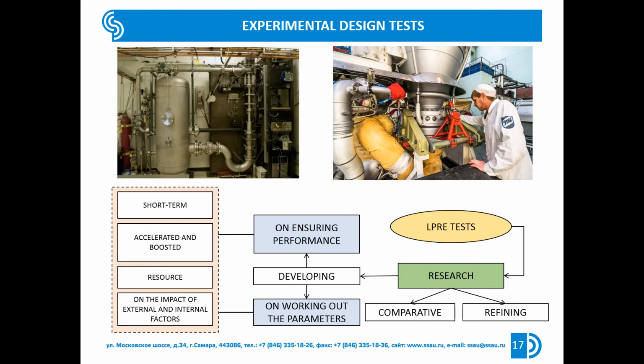In the research phase, comparative refinement and development tests are carried out. The purpose of comparative tests is to accept the best initial variant of LPRE design for further refinement. Refinement tests are tests for preliminary verification of results on performance parameters of liquid propellant rocket engine and determination of possibility of fulfillment of technical specification for liquid propellant rocket engine under development.